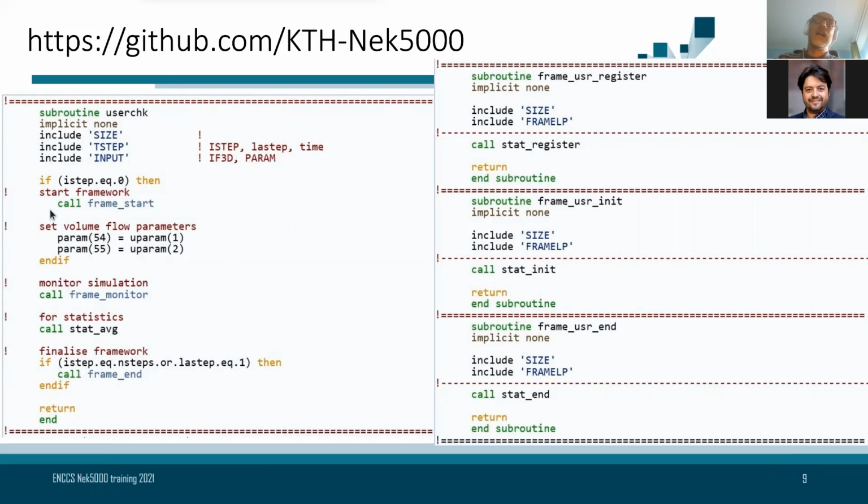Of course, there can be some exceptions, because if you, for example, are calculating SPOD, or you want to calculate the steady state with forcing, then you have to, inside userf, provide a value of the forcing. However, at this point, it will be just reading from the array and placing it in the proper position inside Nek, but the whole forcing will be calculated inside userchk.